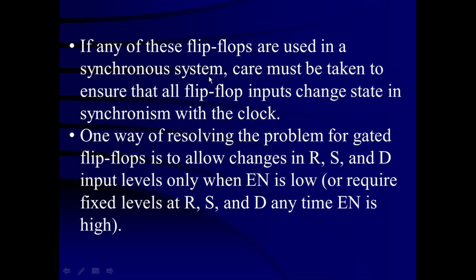If flip-flops are used in a synchronous system, care must be taken to ensure that all the flip-flop inputs change the state in synchronism with the clock. That means all the flip-flop inputs can be changed while the clock is going to be low. When it is going to be high, it has to be maintained constant or fixed. One way of resolving the problem for gated flip-flop is to allow changes in R, S and D input levels only when the enable input is low, or require a fixed level at R, S and D any time the enable input is going to be high.